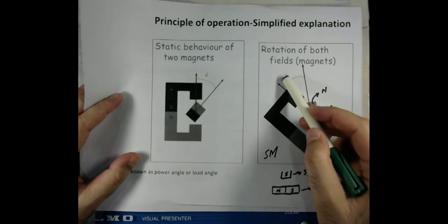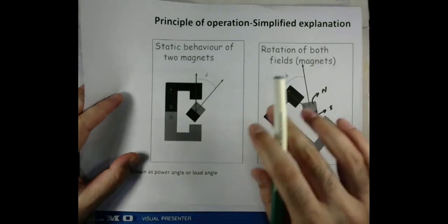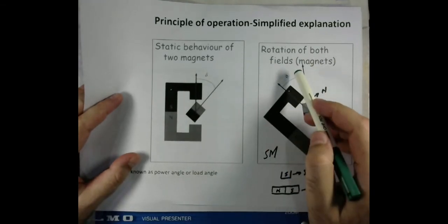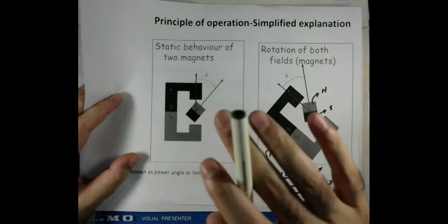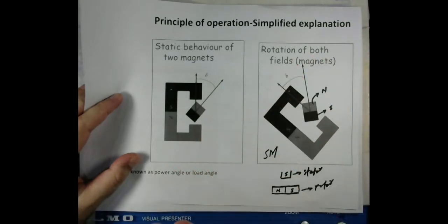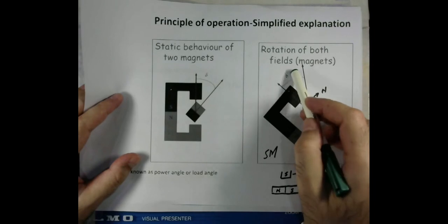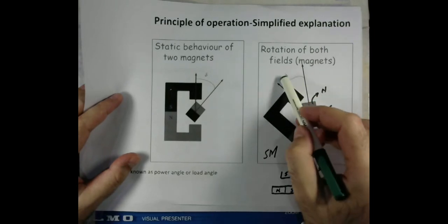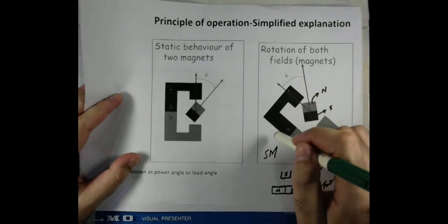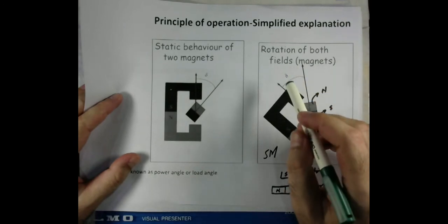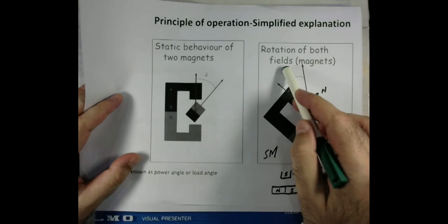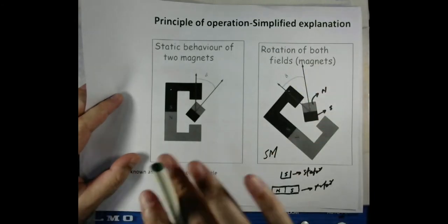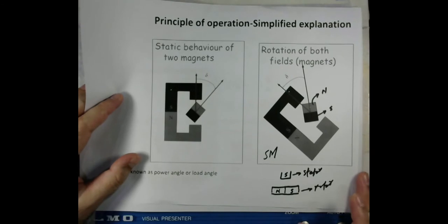So if a machine is running, let's say, at a certain load angle, and if a disturbance appears, there will be change in this angle. And with this angle change, it will change the electrical power, because electrical power, or the active power, is sensitive to the load angle. So it will change the whole dynamics of the system.